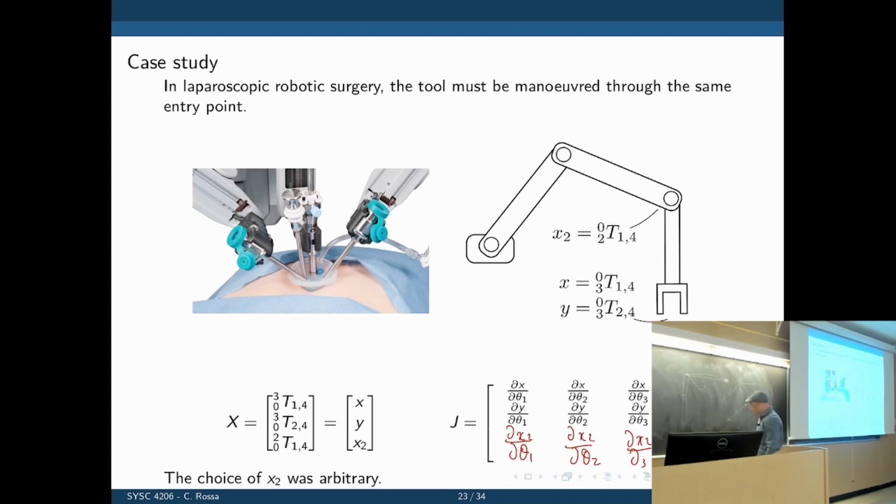Right. So let's say each of these arms here is 1 meter long. I want the robot to go to this point, and this point is 1, 2. There are several solutions for this. You could reach that in many different orientations. But if I wanted to go like this, I can say that the x of this point needs to be 0. Or I could say that the y of that point needs to be 2. If I apply any of these constraints, then that's the only possible solution for that specific orientation.